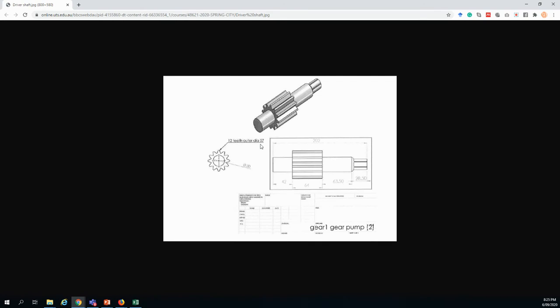By simple research, you will find that the standard diameter we have for the blank material is going to be about 60 millimeters. Thus we need to remove about 3 millimeter out of the diameter, 1.5 millimeter from the radius. That's what we're going to show by the machining in the next stage. So the cylinder to use at the beginning is going to be 210 millimeter length and the diameter of 60 millimeters. Bingo. I can now find the volume of the original part.